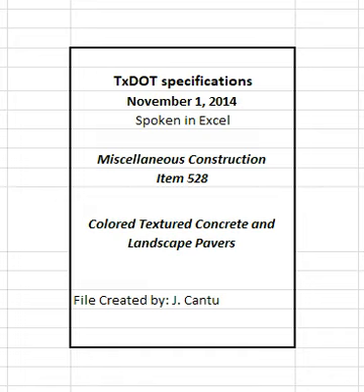For measurement, this item will be measured by the square yard. Removed pavers to be relayed, salvaged, or disposed of will be measured by the square yard in their original position. Replacement pavers will be measured by the square yard in the final position of replacement pavers.